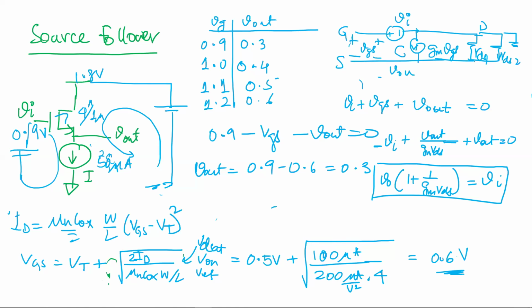Now, that's what's called a source follower amplifier. Source follower is basically, it follows the source. So there is no voltage gain. But can you tell me what's the advantage of that stage? It's not giving me any voltage gain, but it's a very popular stage we use. In fact, in the op-amp architecture I showed you, we use what's called class AB most of the time in high power, but we use this stage a lot. What advantage does this give me?